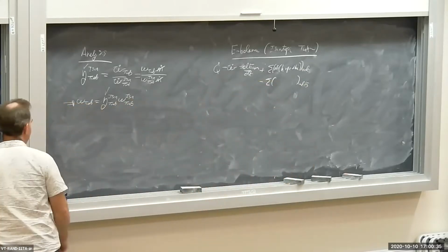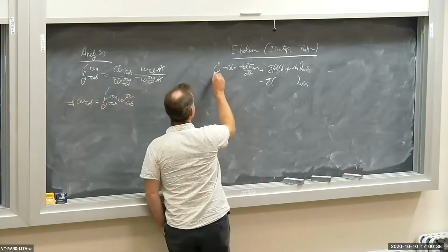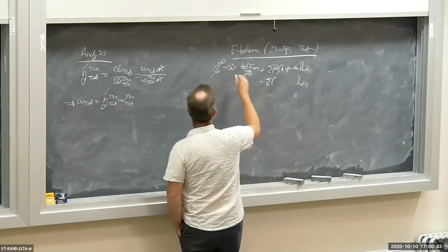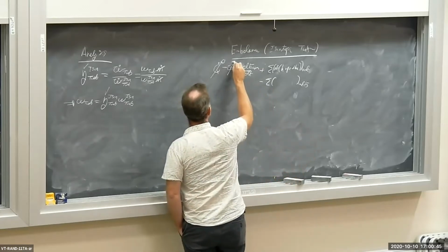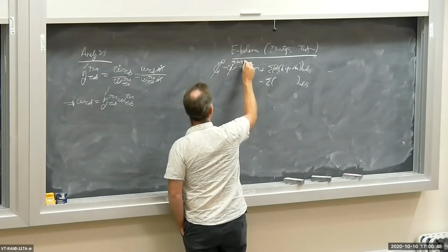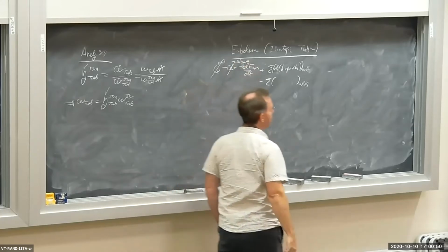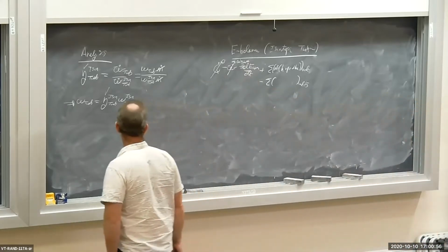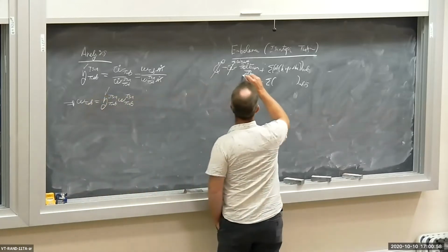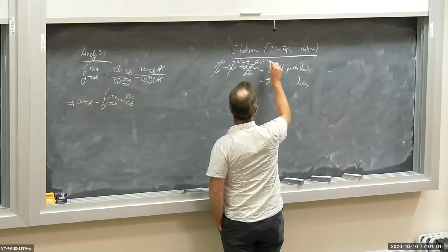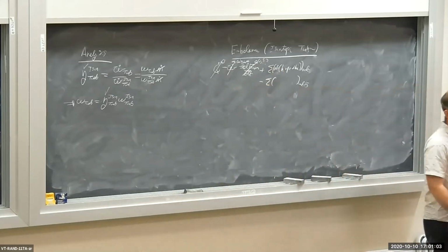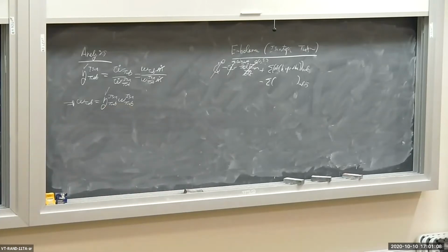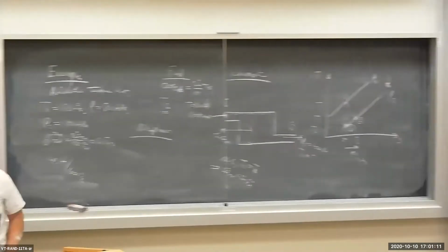Now this is an adiabatic turbine, so Q dot is 0. There's only one form of work, and that's turbine work, or shaft work if you call it that. So this is W dot shaft. It's producing shaft work, that's what the turbine's doing. It's got a propeller in there. No change in energy within the turbine, it's steady state. And I don't seem to have any information on any changes in height or any changes in flow velocity at the inlet and the outlet.